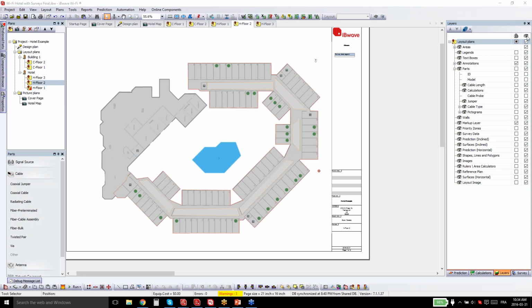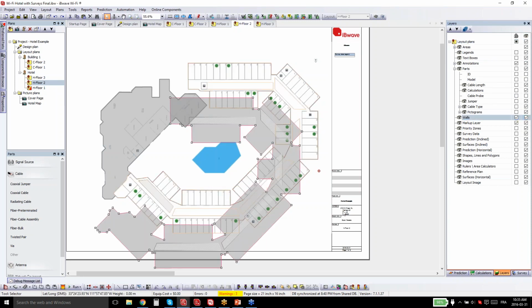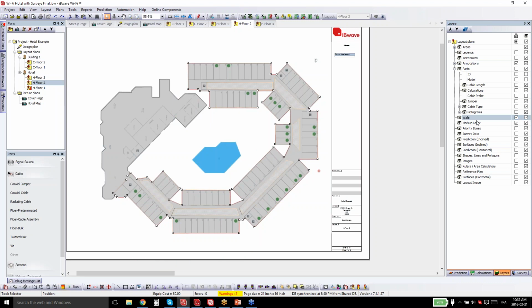So in the layers, you have the ability to visualize and lock different layers. So let's say, for example, I'm done modeling my walls and my floors. I can go over here to the walls and say lock, and I can, whoops, let me just undo that. I locked my walls, but I didn't lock my horizontal image. There we go. So now I can freely work over those walls without messing up my design. So that layers tab you're going to see is going to come in handy as we go forward.